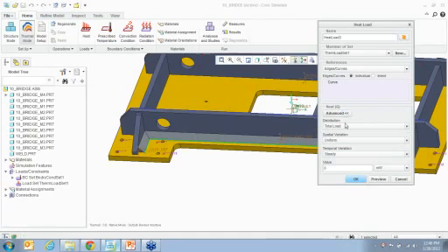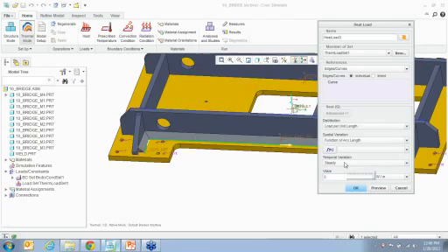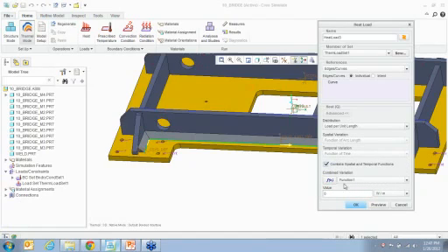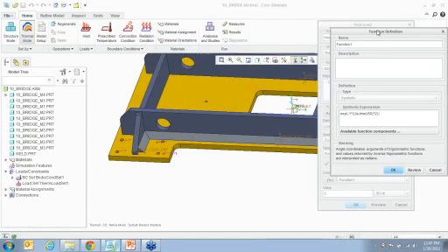Now you can say I want to apply load per unit length, and it's going to be a function of arc length, and the time variation is going to be a function of time. You can choose to combine, notice this, combine the spatial variation with the variation with respect to time. So you can combine them, which is also another enhancement within it. So you can look at the function.